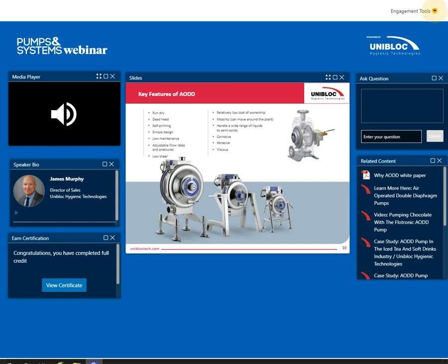The pumps are considered self-priming, usually up to 14 to 15 feet. The simple design, as you see pictured here with this particular pump, is held together by a very large hex nut. There's no tri-clamps, there's no bolts. Literally the entire pump is held together by that one nut there, which makes it very easy for assembly and disassembly.